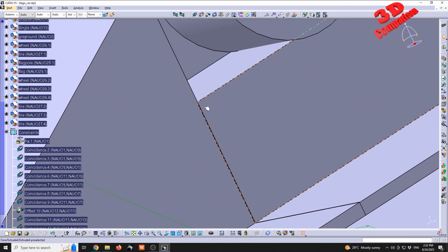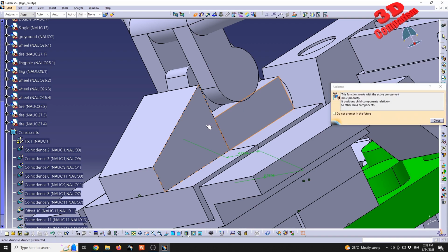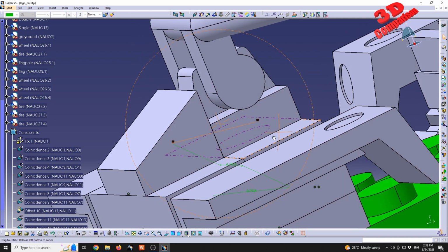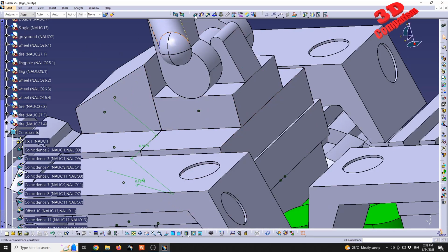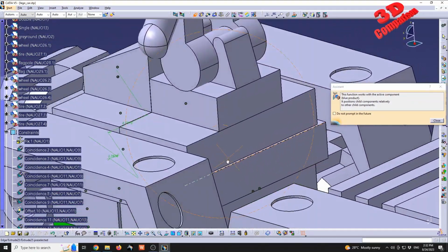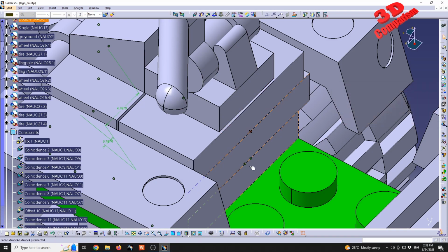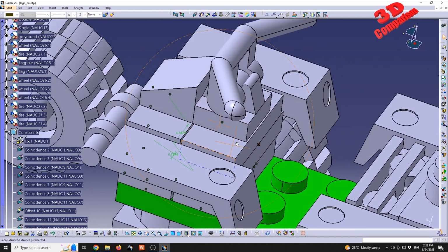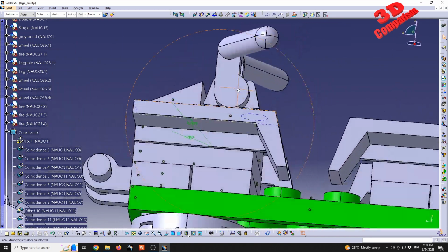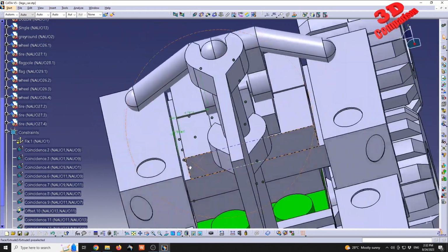For the following components, we see that we have a little gap over there, so I'm gonna put that component to that plane. And afterwards, again, I'm gonna go with the same coincidence. So now we see that this part is a little bit offset. So I'm gonna slightly align that, even though we're gonna have the gap at the middle, just as on the bottom section. I'm gonna leave it like that.